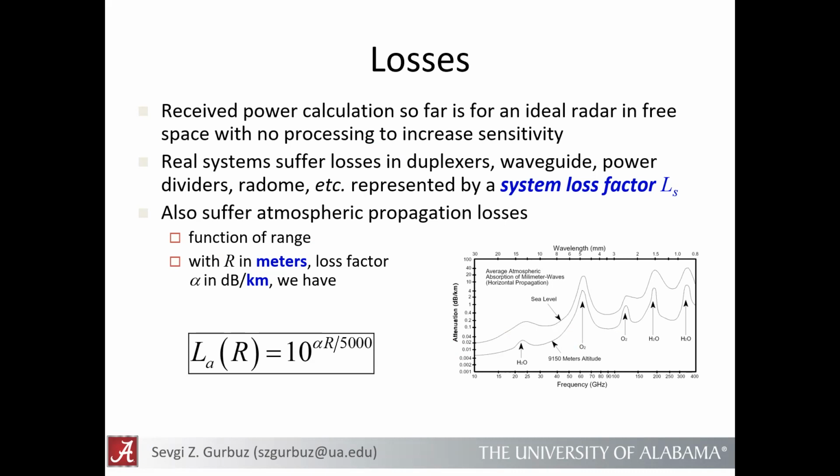But a lot of times there are applications which are nowadays in the millimeter wave, like 77 gigahertz. And the higher in frequency you go, the more the impact of the atmosphere is going to be in terms of reducing the power of your signal, and therefore your ability to detect targets is going to go down with distance. And so usually you'll see that short range radars have these very high frequencies. But if you're trying to do long distance radar applications, such as remote sensing applications like ice sounding and things of that nature, then you're going to use really, really low frequencies, according to what you need to be able to also penetrate the material and penetrate the ground.